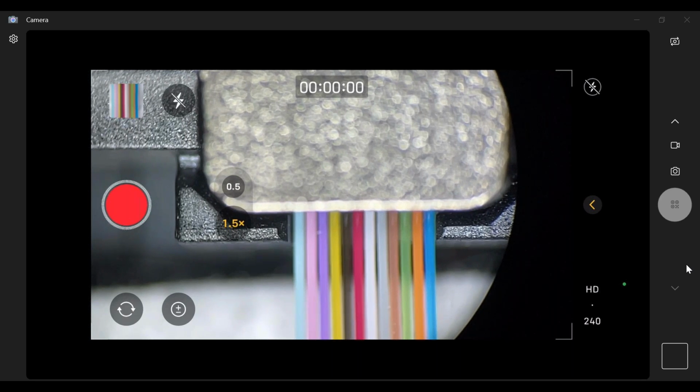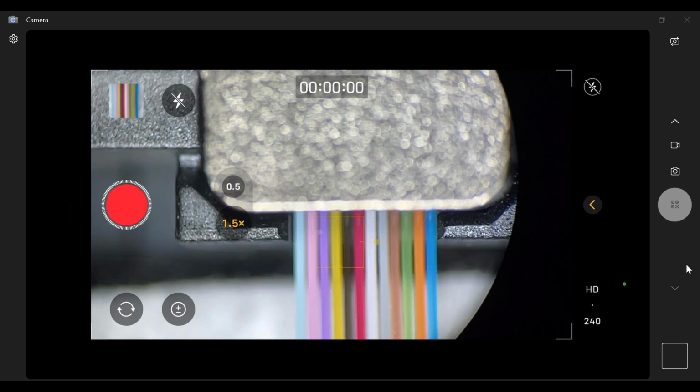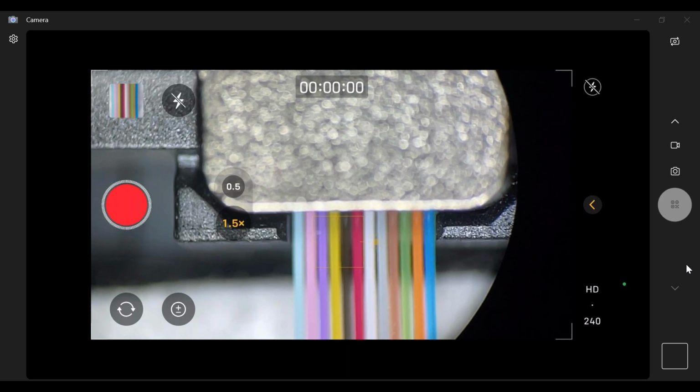This is critical. So when we go to splice this with 200 micron V grooves, you have to make sure that this ribbon array is holding this particular position. This helps you greatly through the cleaving. If you're complaining about your cleaver, this is a big part of it. If you're complaining about your machine not working, getting high fiber offsets, this plays a big factor into it.